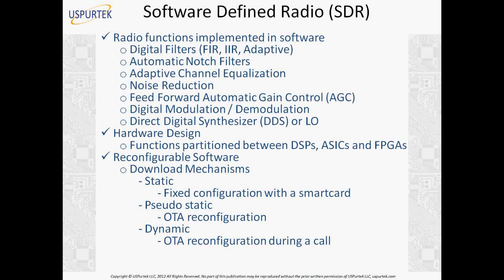We constantly use some hardware implementation to monitor the output frequency, and if there is any variation, we compare with the input. If there is variation, we adjust the oscillator to maintain the frequency at a stable point, whatever frequency it's going to generate inside the receiver. So PLL is used to stabilize the frequency of the oscillator. Phase lock loops provide you a very stable local oscillator. Remember, previously we said that in any wireless receiver, stability is very important. So PLLs help us achieve that stability in the frequency that is generated inside. The same holds for transmitters also.